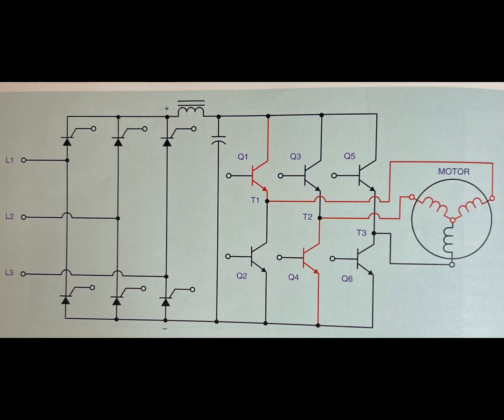As frequency is reduced, the output voltage must also be reduced to prevent excessive current flow in the windings of the induction motor. This method of speed control is frequently used on conveyor systems where it is desirable to have a large number of motors controlled from one source.